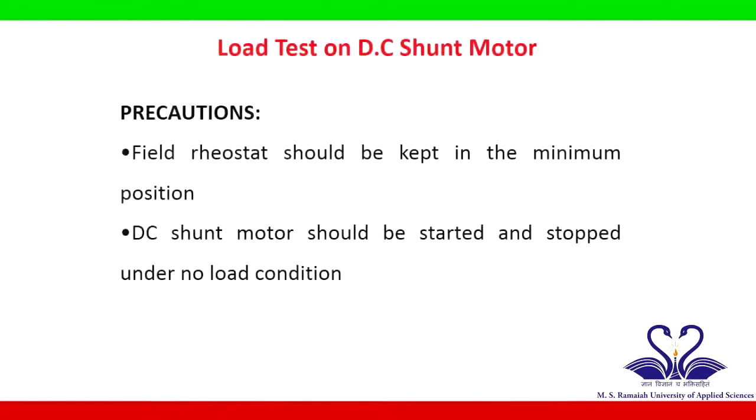While conducting this experiment, we should take the following precautions. Field rheostat should be kept in the minimum position. DC shunt motor should be started and stopped under no load condition.